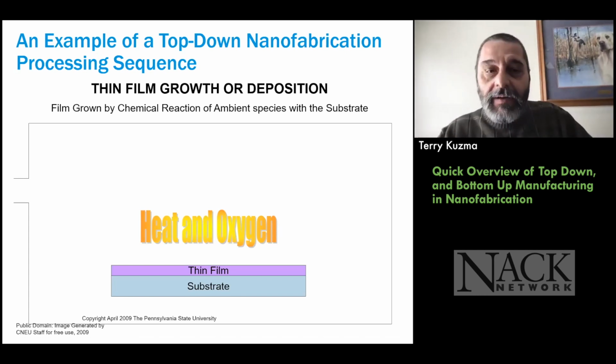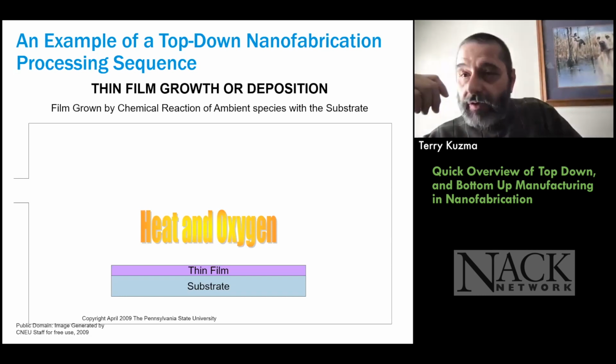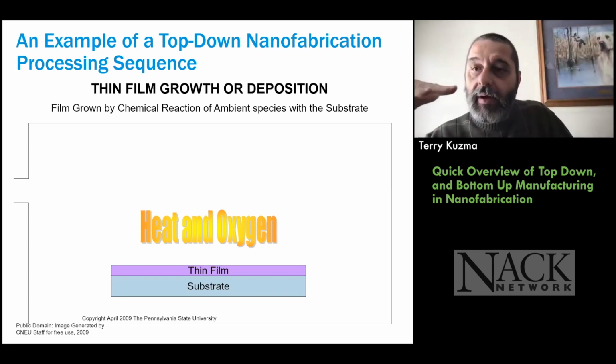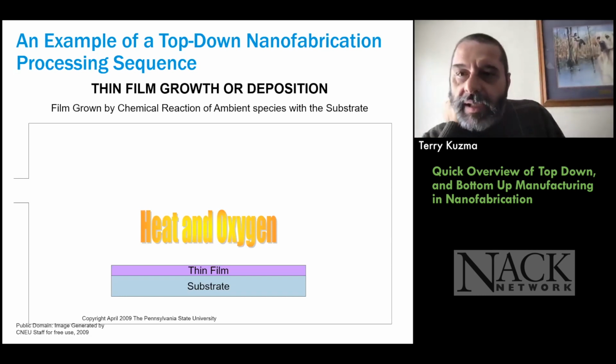But it's really important. And the silicon dioxide is like, I just salute that. That's really important stuff. So we actually oxidize the wafers, and we grow this oxide from the silicon. And we generally do that at temperatures of 900 degrees C.